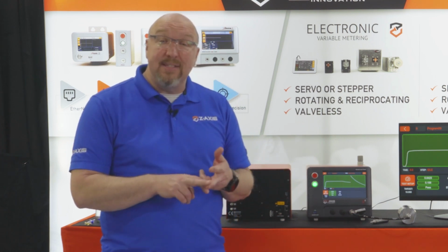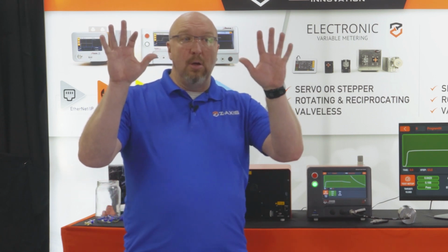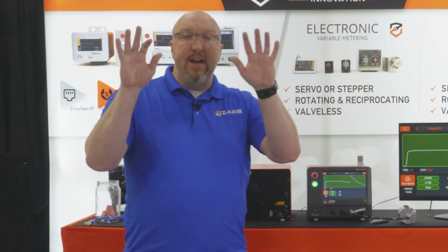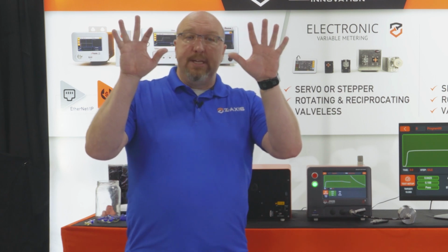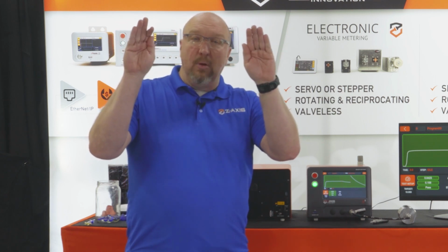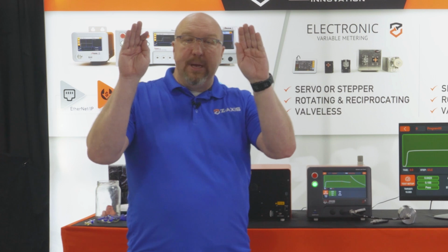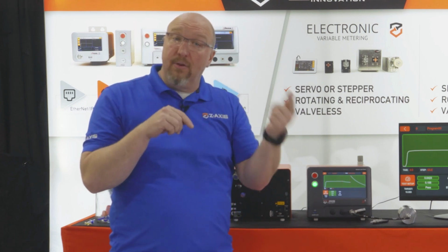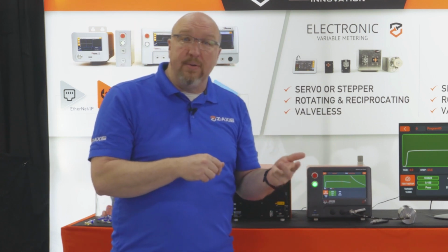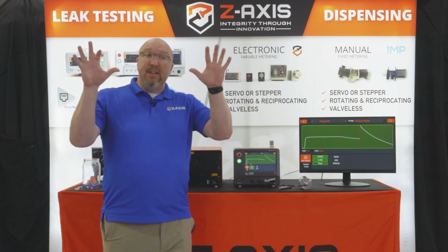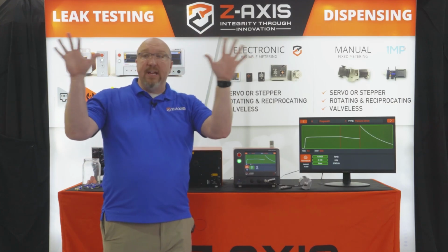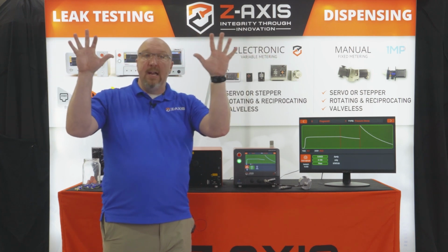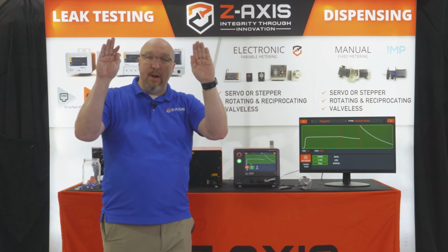Those 2 timers are going to be the fill timer and the test step timer. What they're going to be doing is, if we took our values on a number line and graphed the values we got, we want to get our parts to start getting more repeatable, closer to each other, so that we're getting a very repeatable test. Because we're nullifying the thermodynamics and the elastomeric creep that we've talked about previously. So by changing the fill time, I now take the variance of what those parts could be on the number line, and I start to shrink it and bring it down.